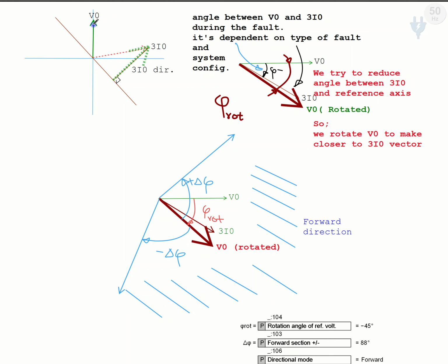Here we had one reference voltage V0 as an axis, which we called the real axis, and the current 3I0 was taking place during the fault. We provided an axis of symmetry and projected 3I0 on it, and the diagonal part on this symmetrical axis was taken for our direction determination. This part is decisive, we said.